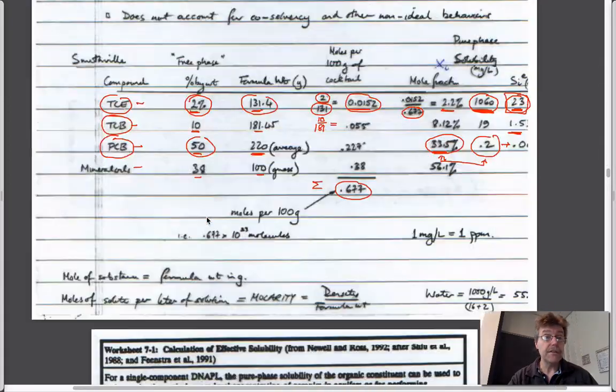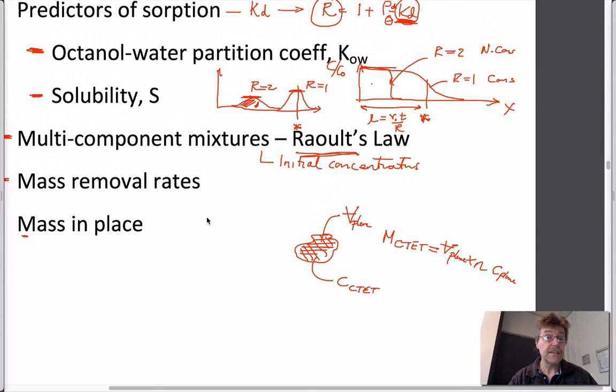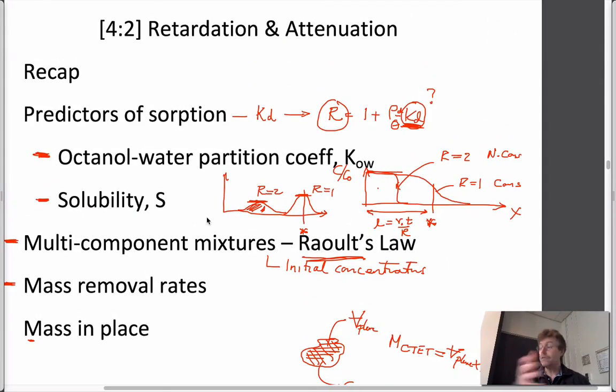So that's really all we'll talk about in terms of mass transport. And so we've talked in great detail about how to define behavior of conservative systems. We've talked about how to calculate what retardation does and why it happens in a mechanistic way, to figure out exactly how we can represent that using the models we use for conservative transport, and from that to be able to make predictions about how much is in place, what the concentrations should be, how fast it will travel downstream. And that's the precursor to be able to say something about how we might be able to remediate things by sucking it out and how quickly we might be able to do it. So I'll leave it at that. Great, thank you. Sorry.